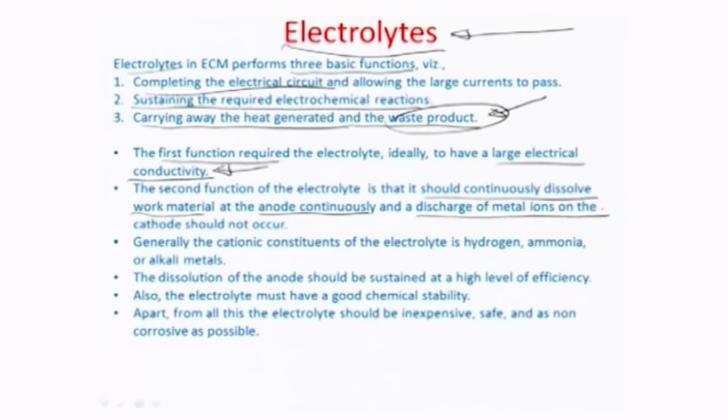it should discharge the metal ions that come in by virtue of some chemical reactions, thus leaving no residue on the tool surface. So, whatever ions are emanating from the workpiece surface should be able to get chemically dissolved within the electrolyte system. The electrolyte is a sort of barrier between the material that gets transported from the workpiece and the tool.